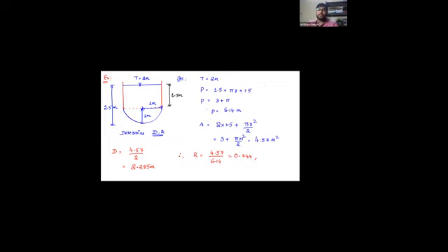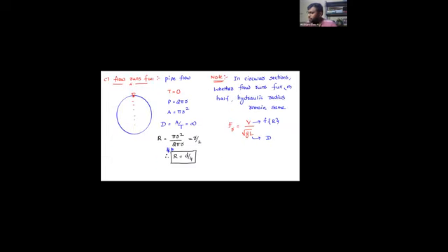Yeah. So that's about the channel geometry. And with this, we have covered the introduction, types of channels, and cross sections. In order to classify the flow, I hope you now have an overview, because the type of flow depends upon the Froude number, and the Froude number is a function of whom? Hydraulic radius and hydraulic depth. So as the type of channel section changes, the hydraulic radius and hydraulic depth also change, and then obviously the Froude number also changes. Okay. So now let's see what this Froude number is.